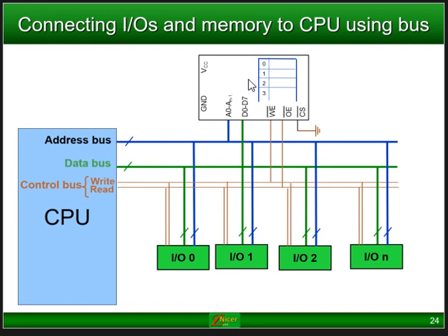The memory device is now connected to the address bus, also to the data bus, also to the write enable line, to the read enable line, which is the same as the output enable. And in this specific case, this device is connected to chip select. This device's chip select is connected to ground, which means this device is actually active the whole time, which is not a very healthy condition. And you'll see that in the next slide it is going to be changed, because that is not what it's